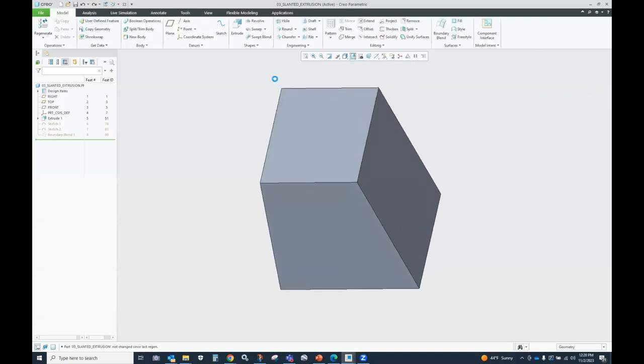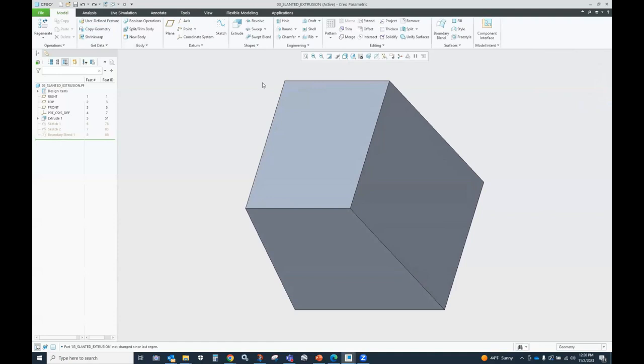Okay, now I mentioned earlier, I got about 10 more minutes, which is perfect. I mentioned earlier that when you create a reference, whether it be a datum plane, an axis, a datum reference feature, create it when you need it, right? Because if we create these datums that are only used for one feature, then we got to manage them in the tree. We have to manage them with layers. I mean, nobody likes to go into an assembly and see a rat's nest of datums, right?